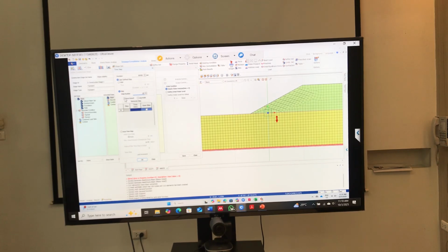So I can check displacement or other results after that. If I do it like this, it's 1 day, which is not too much for real life situations. Of course, it cannot rain the whole day, maybe 8 hours. Then you put it at a 1 hour interval. If I do it for 1 year, it would be 365 days times 24.